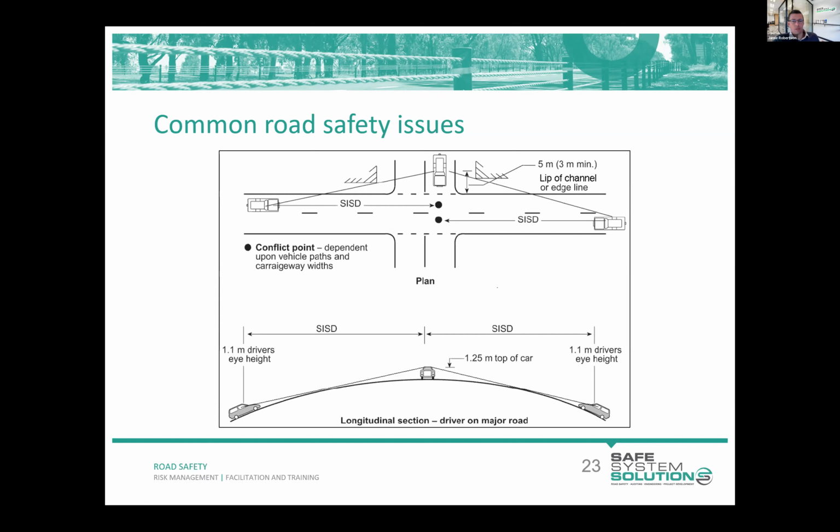Yeah, so there are different radii for different vehicles. 12.5 and 15 metres are pretty common radii that we do use. Shorter vehicles can turn on some smaller radii. So it's important there to look to the Austroads Guide to Design Vehicles and Swept Paths.